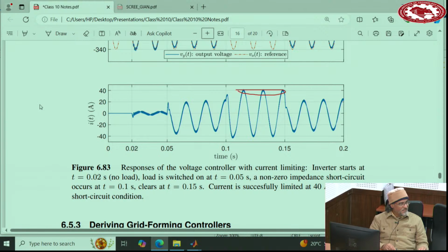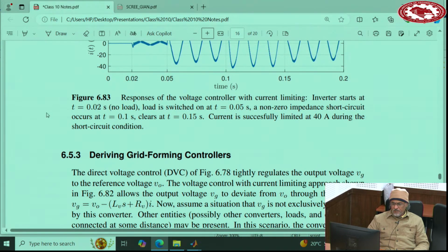And by the way, the challenging part is the damper windings. People still have a lot of difficulty modeling the damper windings on the synchronous generator. So that's the difficult part. But anyway, if you manage to do it to a certain extent, now all those equations, dampers and other parts of the machine, synchronous reactance, windings, just implement all these in your inverter. It will eventually be very similar to the VSM that we had here. But this is another approach.